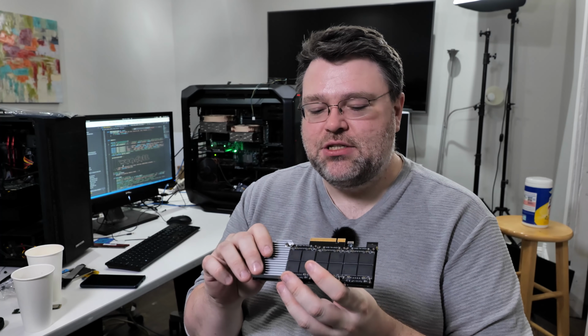And a lot of the time when one sector, one logical block address, I call it a sector, is replaced with another sector, it does a little bit of invalidation. So at a minimum, the error correction information will fail. And so if you're looking at two different sectors and the ECC information in this one is correct, but the ECC information for this one is incorrect, that gives you a clue as to which sector you could go with. I have no idea how to find or decode ECC information on this. Since I've been able to dump 1.5 terabytes of data from a 1.2 terabyte card, I am pretty sure that I've got the error correction information. I just don't know how to decode it with the information that I have.